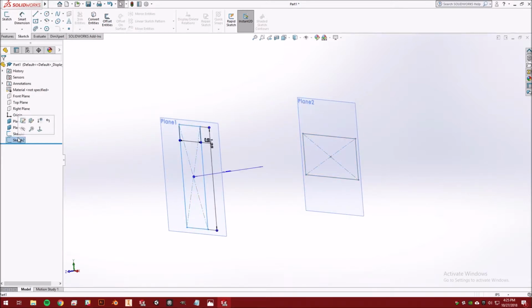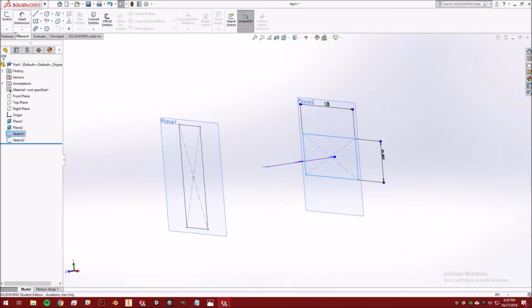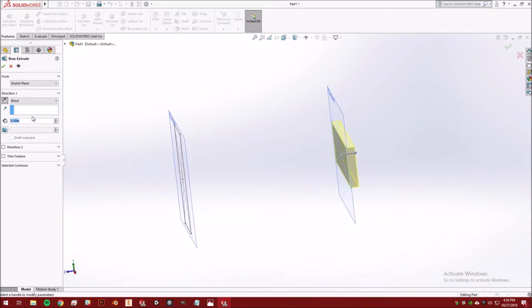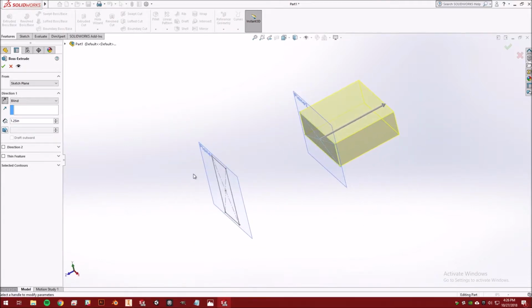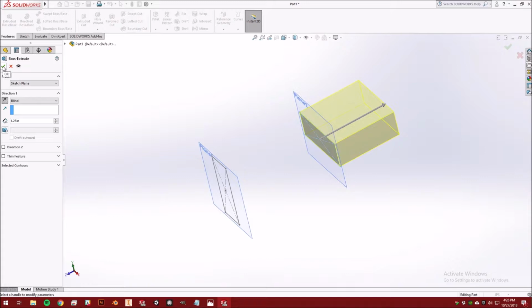Now we've got two sketches here, and we can go ahead and make this top half on each sketch. This extends out 1.25 inches, since we have 1 inch, 1 inch, and the whole thing's supposed to be 4.5. So we'll go out 1.25 inches, that's under Features, Extruded. And you want to make sure it's going the right direction. You want it to go out this way. So we'll go ahead and flip that, and then change this to 1.25. Alright, there we go, that should be correct, 1.25, and we will hit Done.